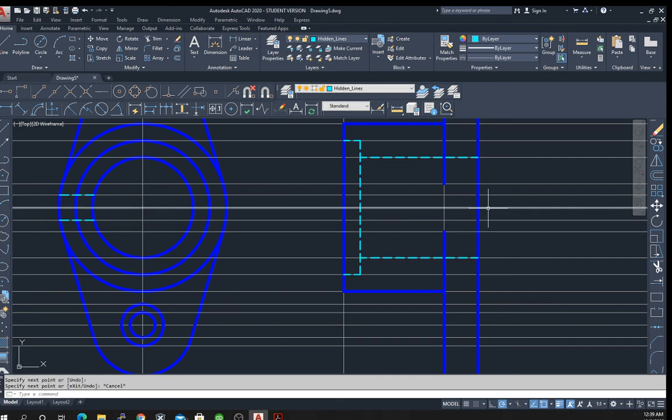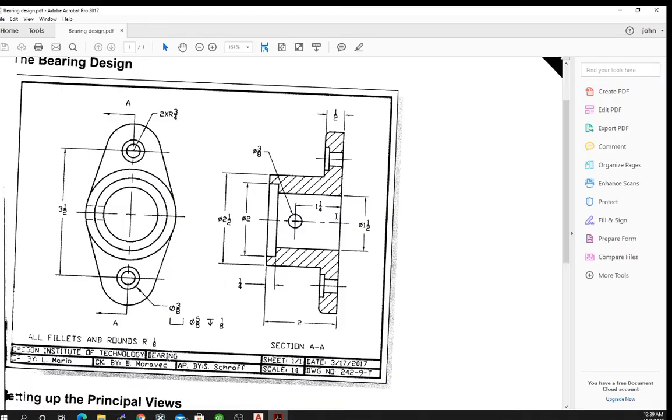And then centered in the drawing, 1.25 inches. Let me come back to the drawing. 1.25 inches from this point, we're going to have this 3/8 of an inch hole, or this 0.375 inch hole. That is also hidden. At least right now it's hidden.